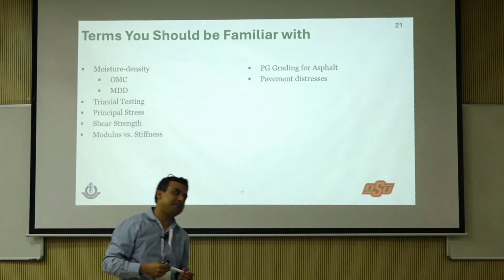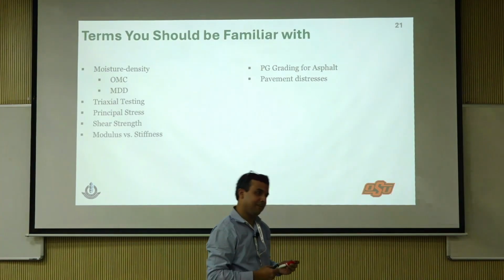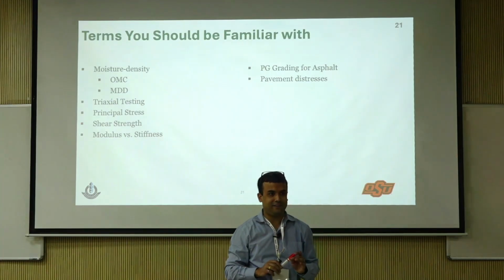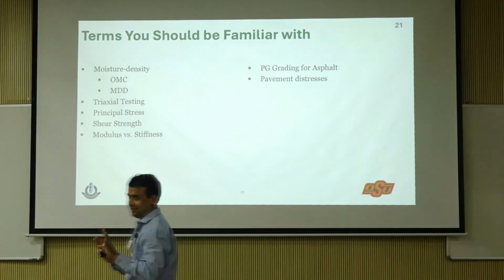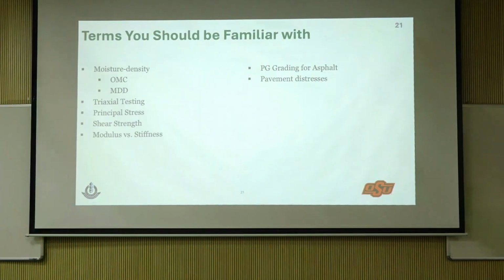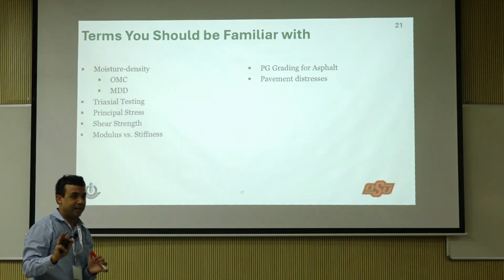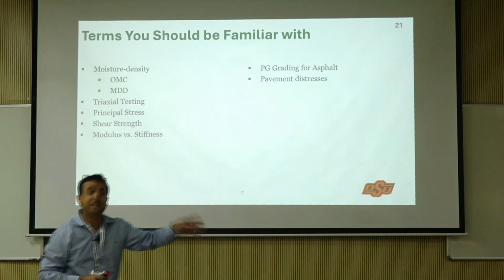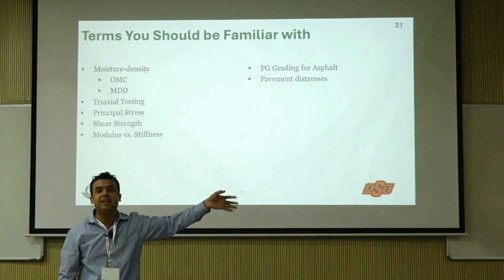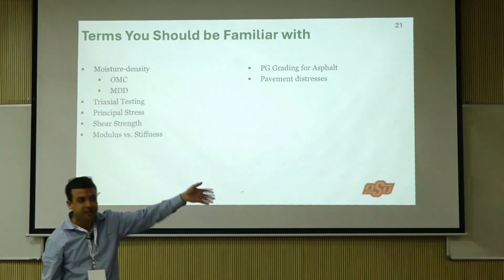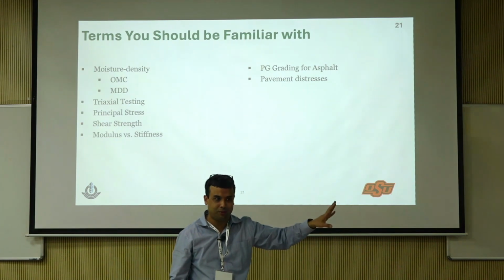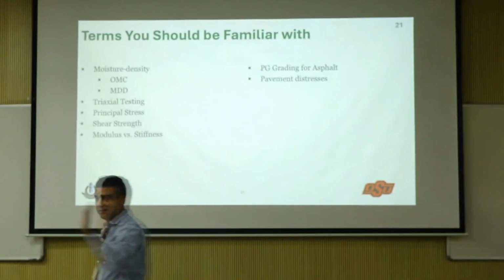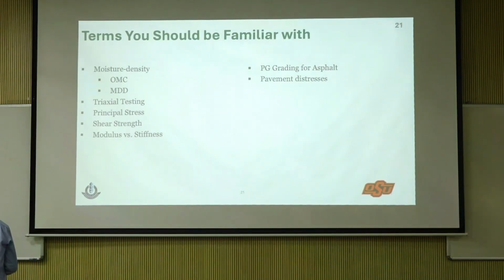So we are doing an elastic analysis to predict plastic deformation, right? As long as we know our limitations. We are doing an elastic analysis and predicting plastic deformations. Just know that. Why? Because doing plastic modeling is extremely difficult. It is prohibitively difficult. That's where the practicality issue comes into the picture. We are not going to be able to do that. But we need to remember there are differences. We need to worry about those things.